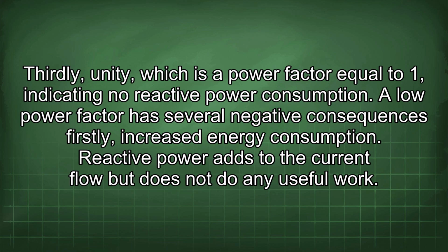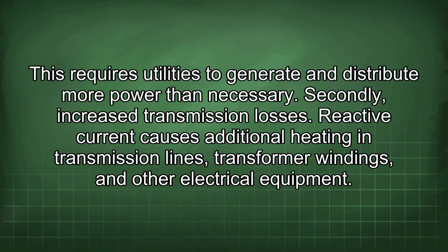A low power factor has several negative consequences. Firstly, increased energy consumption. Reactive power adds to the current flow but does not do any useful work. This requires utilities to generate and distribute more power than necessary. Secondly, increased transmission losses. Reactive current causes additional heating in transmission lines, transformer windings, and other electrical equipment.